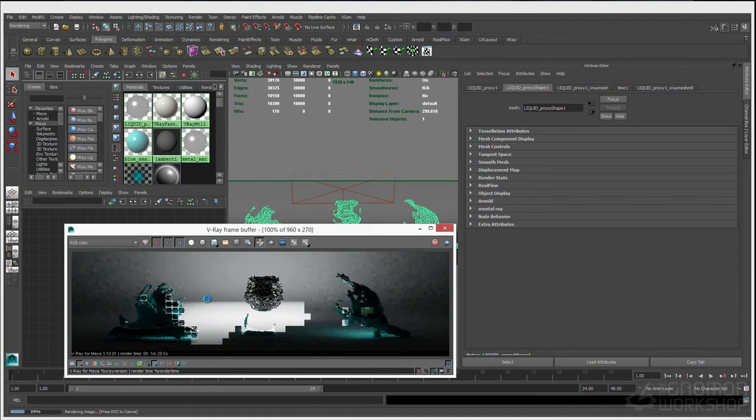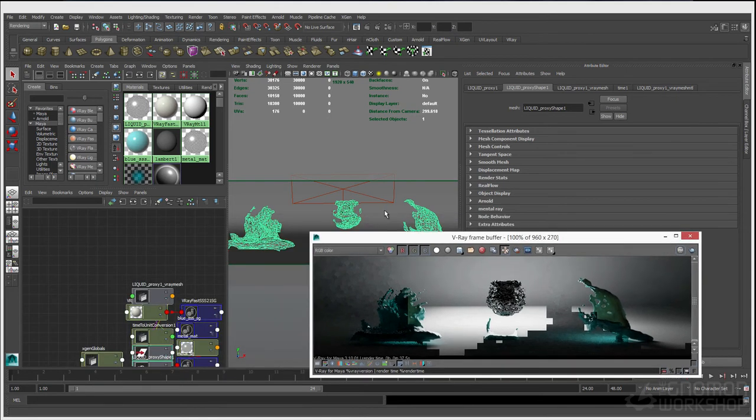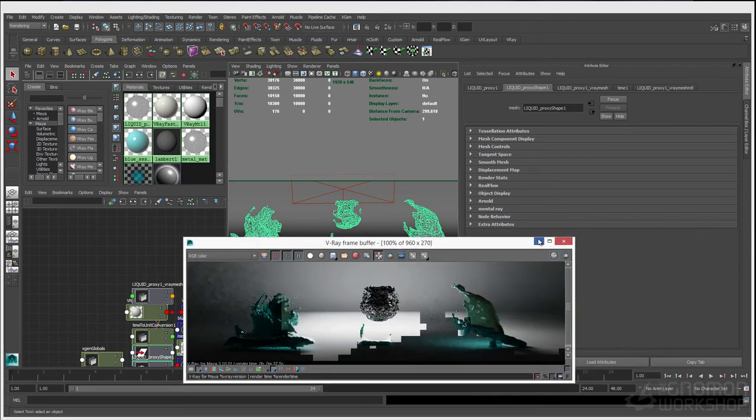So you may be asking why this is such a big deal at this point, but if you remember how dense that geometry really was, you're really going to be saving yourself a lot of headache when you're dealing with really large, dense groups of geometry. Going in and having your objects baked out to Vray proxies can be very helpful because you can still have the ability to have large sets of geometry in your scene without having to actually view them in the viewport. So let's actually take a look at how this works.